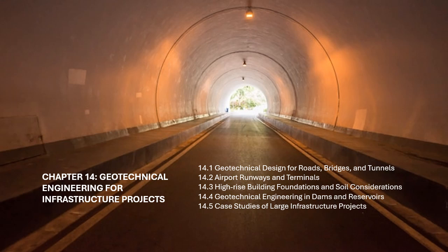Uncertainty in subsurface conditions. Subsurface variability often leads to uncertainty in the design process. Geotechnical engineers must account for soil variability and adjust designs based on a combination of field data, laboratory testing, and experience. Stochastic modeling and probabilistic design can help quantify this uncertainty and guide design decisions.